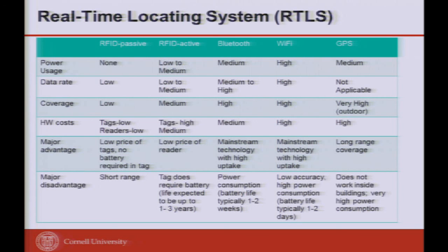Okay, but there are many locating ways. I see a lot of work in your previous review. Let's not look at this. Only looking at RFID passive mode, you can get it from the signal strength, or you can get it from the phase difference. Signal strength has a lot of problems. With phase, you have to deal with the fundamental issues of bandwidth and what they call wavelength ambiguity.